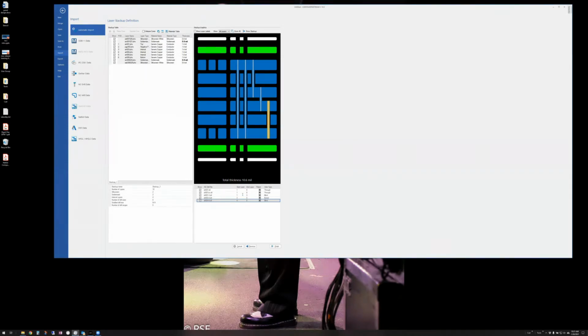The next thing I'm going to talk about is the drill files down here, and you can set the plating characteristics. And the reason you would do that is so that when you run any analysis, that it knows whether the drills are plated or unplated. Now, this particular design has a separate unplated layer, so you can see I made it that way. By the way, there's nothing in the drill file that tells us if it's plated or not. That's not per the Excellon spec. Some drill files have comments, but they're not per any spec. So when you load a drill file, you have to tell the software whether a hole is plated or not.